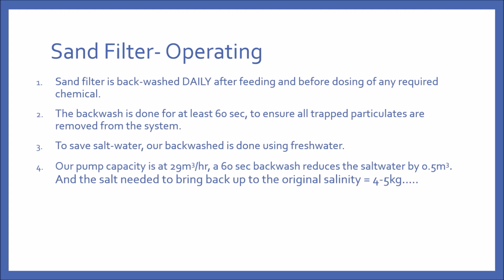However, by doing backwash on a sand filter system, you usually tend to use system water to perform the backwash, which for some of us can be quite costly, especially if you are located far from the coast. So one way of doing it is to change the piping, so that when you're about to backwash, you swap the piping into a freshwater line and use freshwater to backwash.